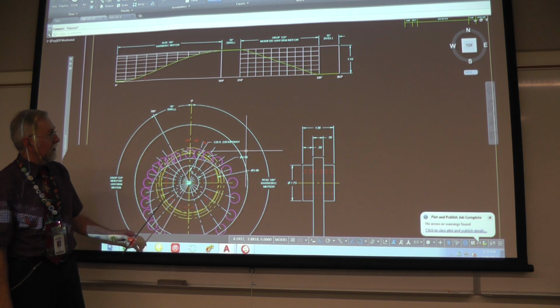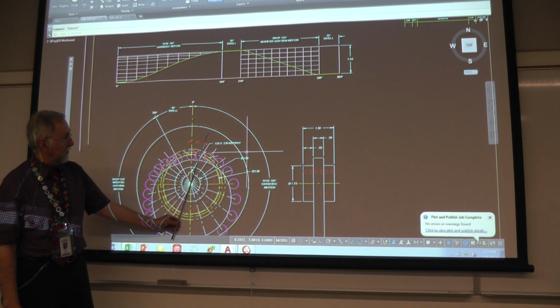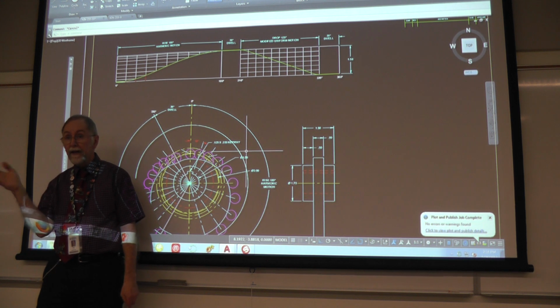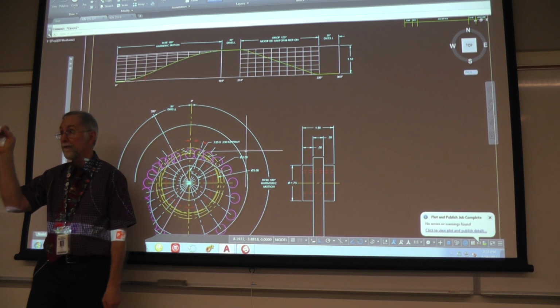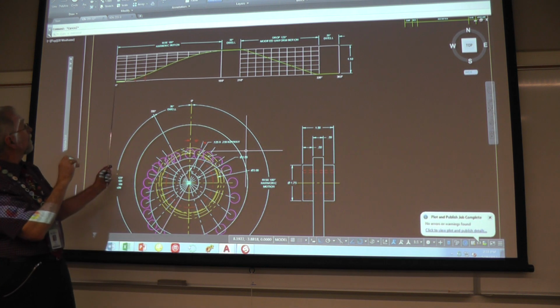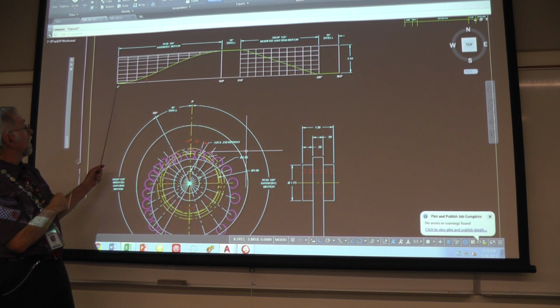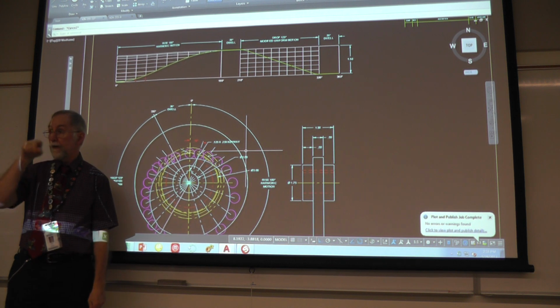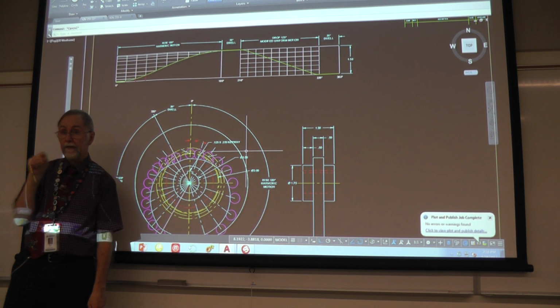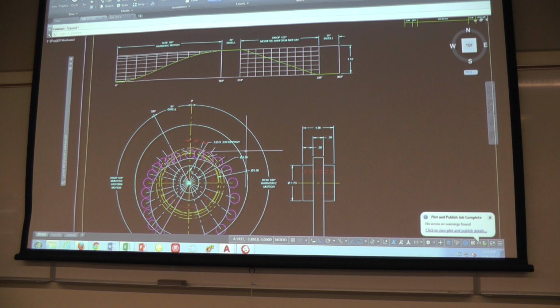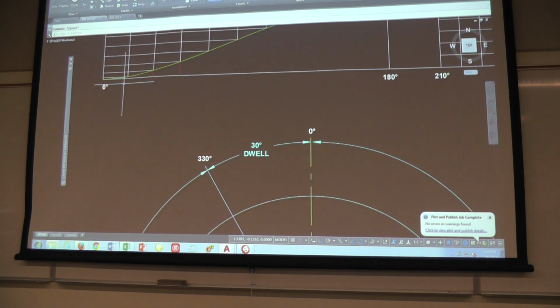Right. Okay. The 18-degree increments mark where the center of each roller position is going to be. And it needs to increment out a certain amount from the starting point, which happens to be this 0 degree right here. And it's at rest, so the profile starts right on the edge, right at the bottom of the profile diagram. Okay, first increment over, 18 degrees over. Unfortunately, there's some construction work that you will have to do. That's just the nature of the game. All right, the first increment over.